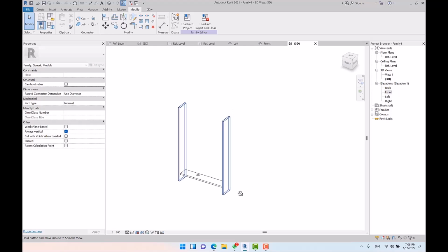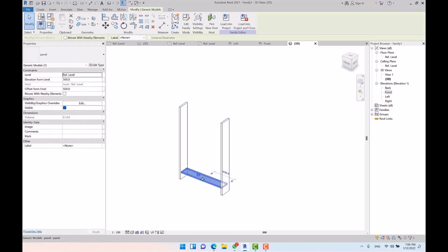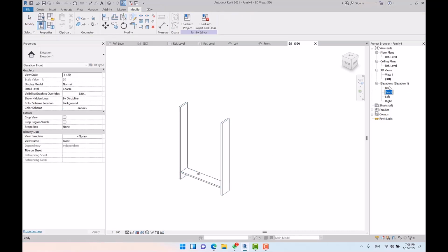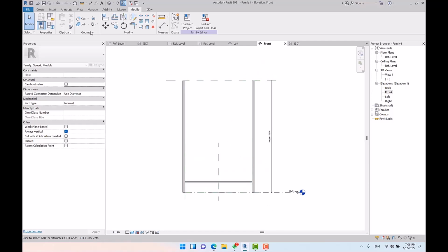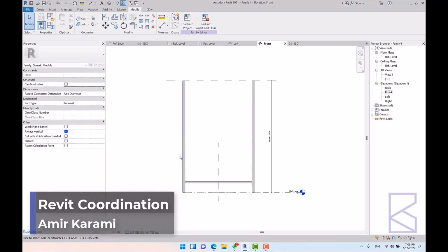Check it out. We got the lateral walls and the shelf, or the panel actually. We got extrusions in the lateral walls and the panel with the hole or opening. Until now everything is okay. Don't forget to associate the parameters. Then the panel here is ready to be duplicated or arrayed.